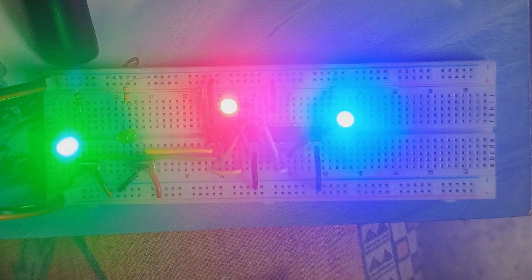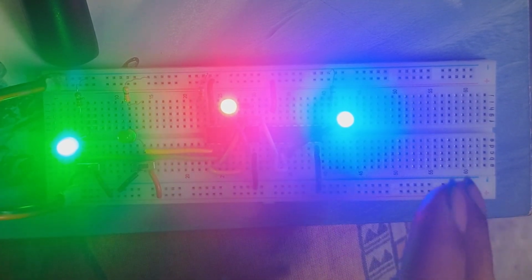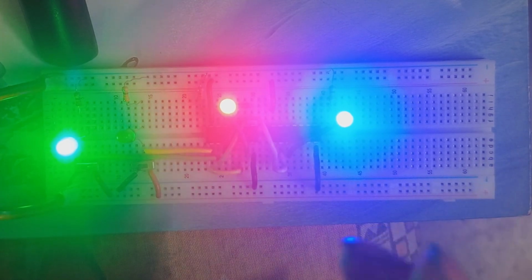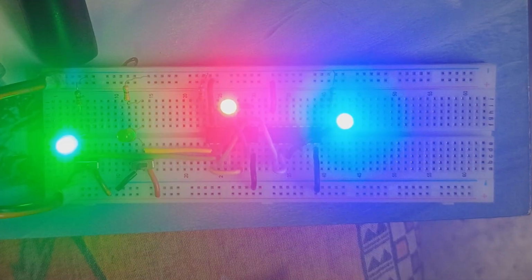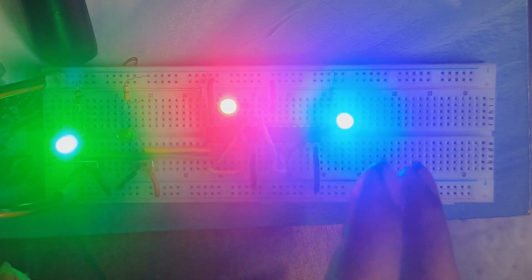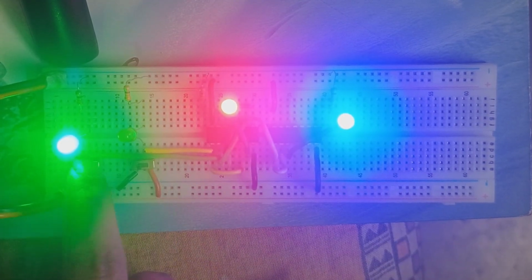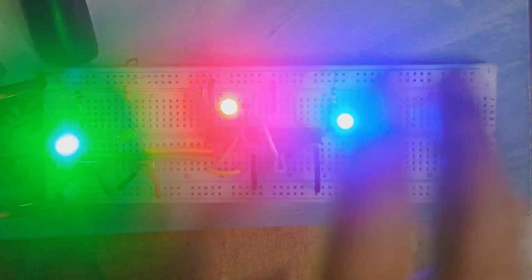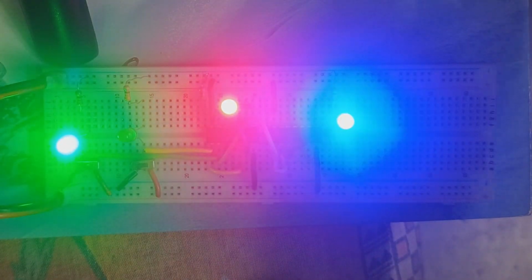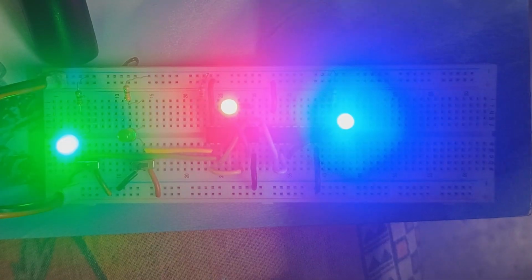So these are the total 4 conditions of binary subtraction, and this is a half subtractor, not a full subtractor. In the case of a full subtractor, there will be 3 inputs, with a borrow in from the previous stage. In a half subtractor there are 2 inputs, input 1 and input 2, and 2 outputs, difference and borrow. This is a very similar circuit to a half adder, and nothing special here.